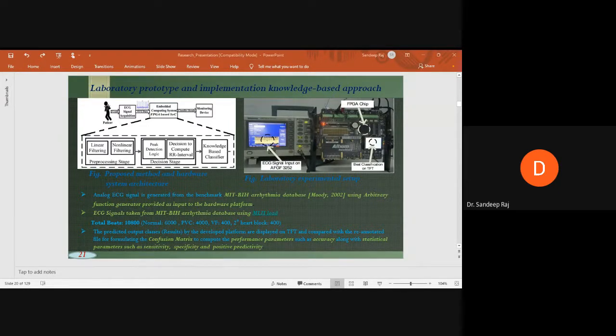So in this case, the length of the ECG signal was 256. So we reported the computational complexity and the number of computations required to perform this FFT-based DWT algorithm. Finally, we obtained 18 coefficients as one feature vector to represent each of the ECG signals. And then again, we use the BPNN network to classify this, and finally it has been implemented on commercially available hardware platforms.